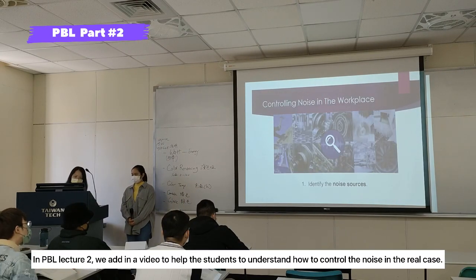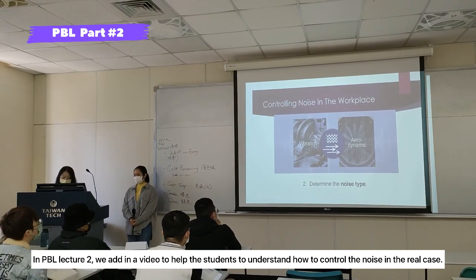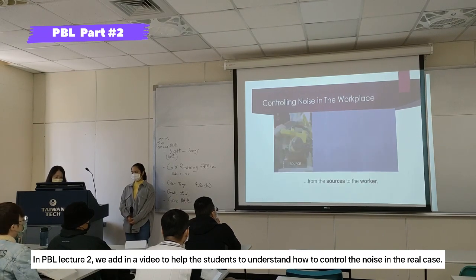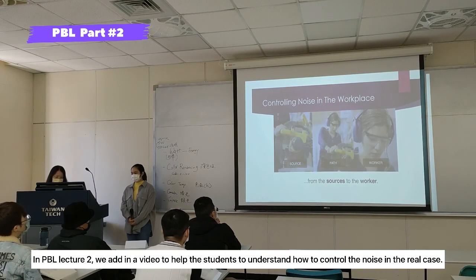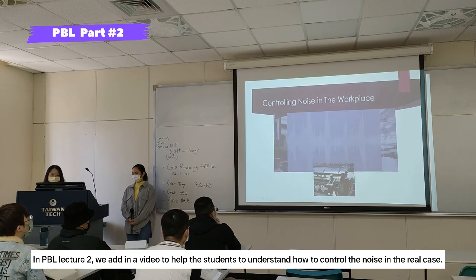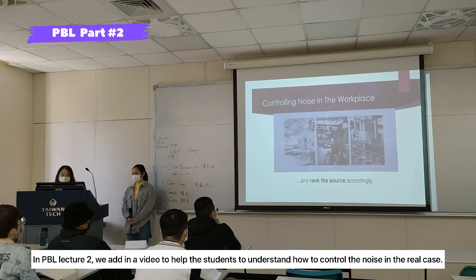Identify the noise sources. Determine the noise type. Identify the noise paths, from the sources to the worker. Determine the noise level of each source. Determine the relative contribution of each source to the excessive noise, and rank the sources accordingly.